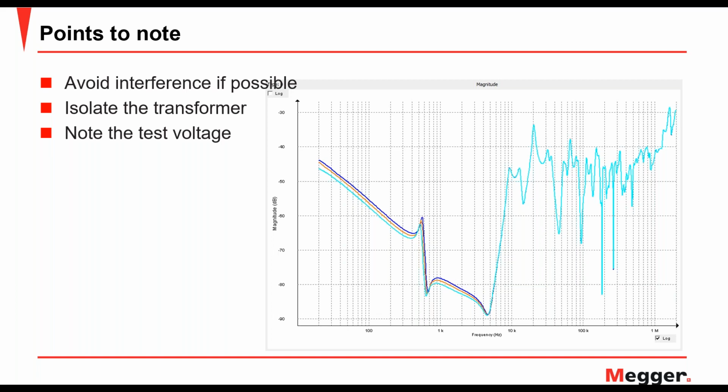One way of looking for any disturbances is by doing a single point test, where you connect both leads on the high voltage bushing that you're testing on. Just one high voltage bushing. So both leads are connected on the same high voltage bushing, and you run a measurement. The response should pretty much be at 0 decibels, but at higher frequencies, you'll see that it starts to deviate, and that's the point at which I guess the noise plays a role in influencing the measurement.